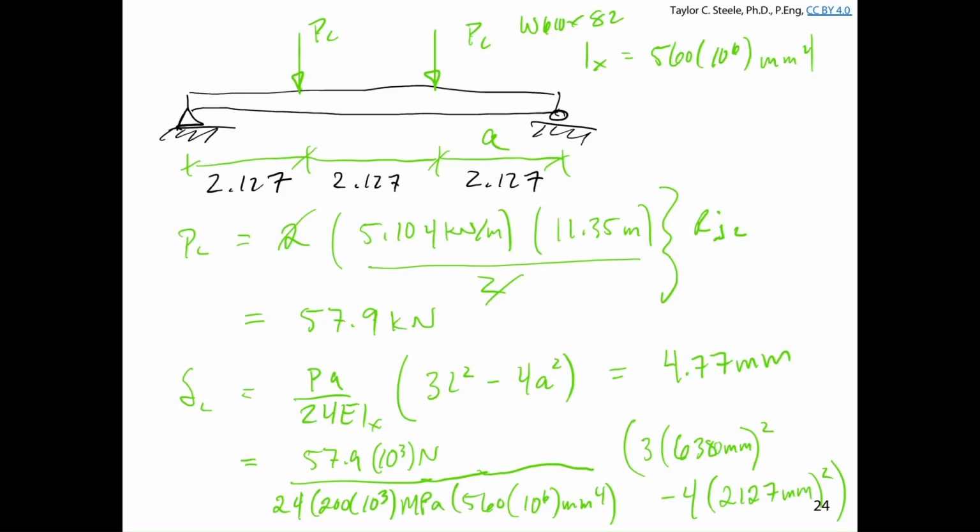What do you think, or maybe before I write anything else down, do you think that's acceptable compared to what the upper limit on that girder would be? I would think so, right? Let's just assume that the floor is susceptible to cracking, so we want L over 360. That's equal to 6,380 over 360, which would give us a limit of 17.7 millimeters.